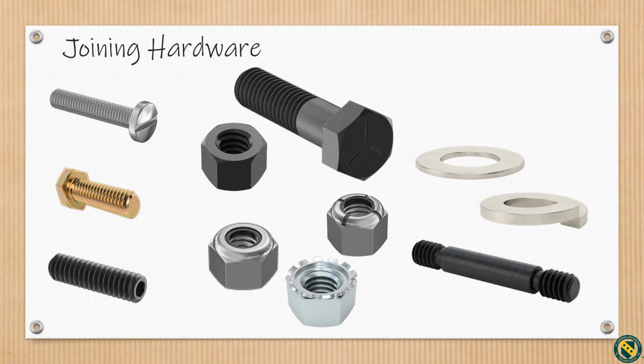A bolt is the term used for a threaded fastener with a head designed to be used in conjunction with and properly assembled by means of tightening a nut. It's common to use the terms screw and bolt interchangeably. A nut is a geometrically designed block, usually of metal or plastic, with an internal thread and designed to be assembled in conjunction with a bolt or a screw. A lock nut has a special design that helps to prevent the nut from loosening.